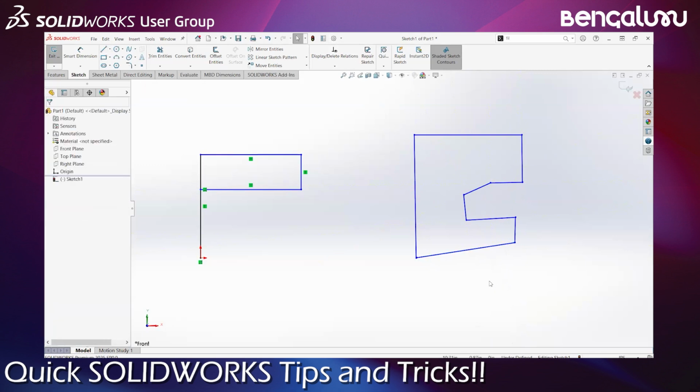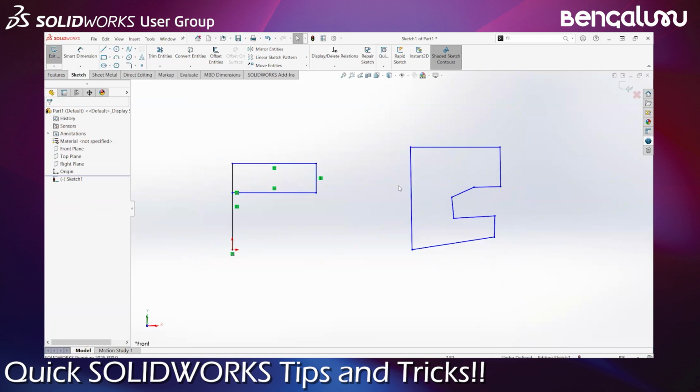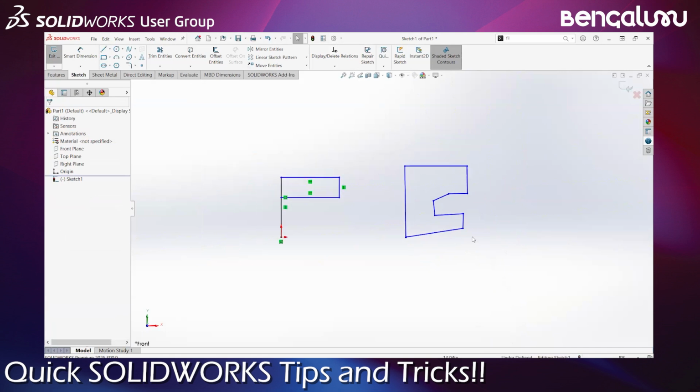So when you're defining a product, you yourself don't know what the constraint should be initially in the conceptual stage. So in that case, for a few of these sketches, you want relations to be added automatically. For a few you don't, then in that case, hold a control key and then draw a sketch. That helps that the relationships are not automatically added, right?